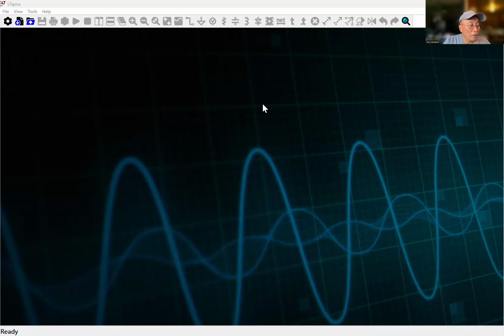Hi everyone. The topic for this video is the RC time constant in the LTspice program. Here we'll explore the RC time constant using LTspice. The RC time constant is denoted by tau, and it describes how quickly a capacitor charges or discharges in an RC circuit. Mathematically, tau equals R times C.